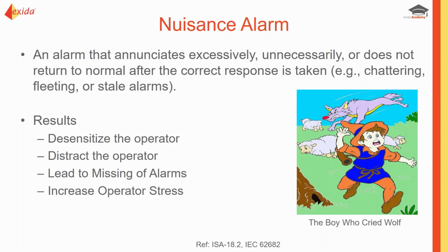So nuisance alarms are very dangerous because they truly can make the operators believe that it's okay to ignore alarms. It desensitizes them, and it also causes a lot of stress because there's typically a lot of extra alarms occurring, making the operating environment very challenging.